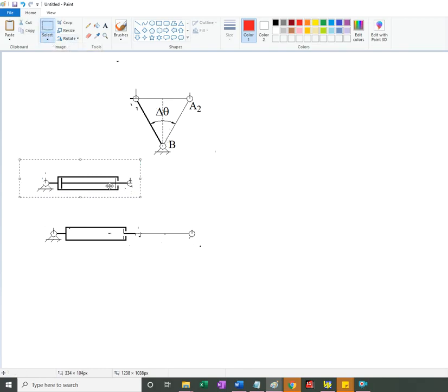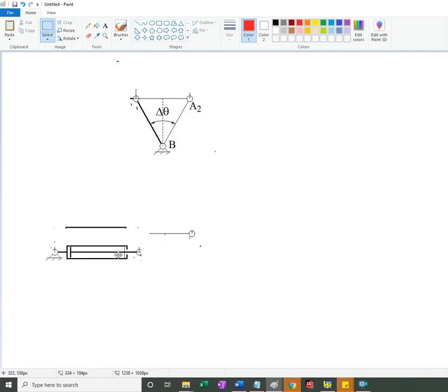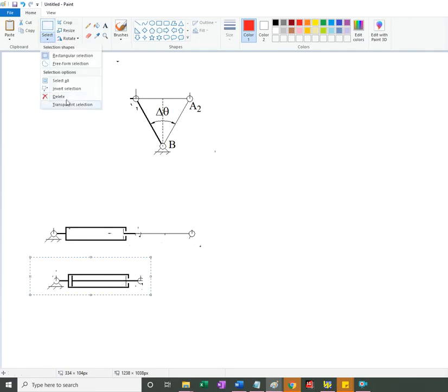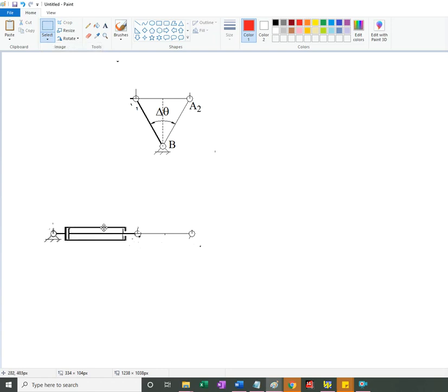Okay, so we start with the actuators, and you take the shortest and longest, and you put them in line like so, and then you want to get point B. So you don't start with point B. It's actually start with the actuator, and it'll be A1 and A2. That's why I started saying find the middle and draw the perpendicular. So you draw the perpendicular to the middle of the segment A1, A2.